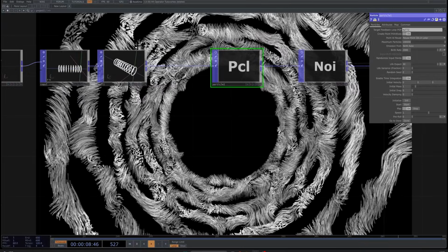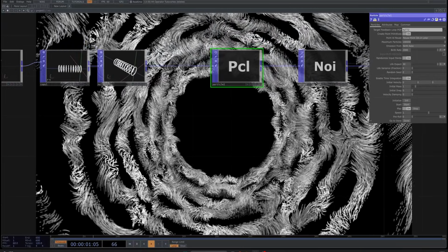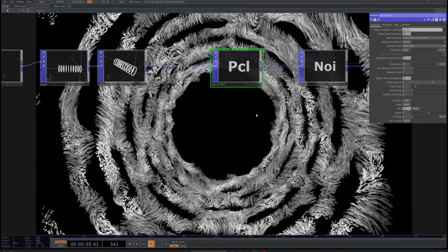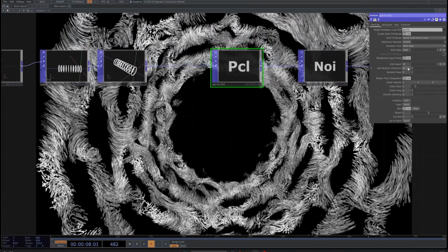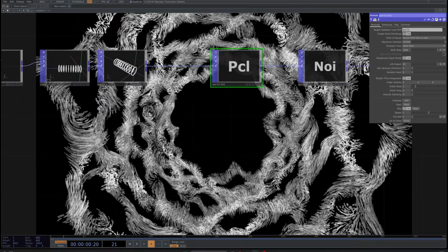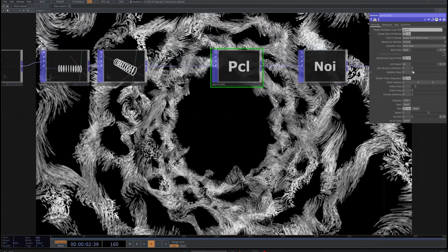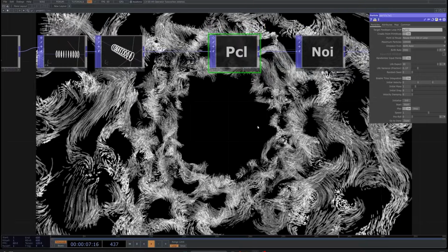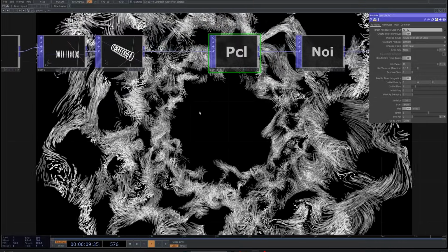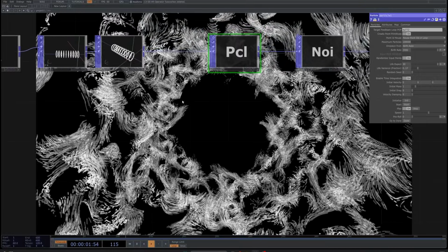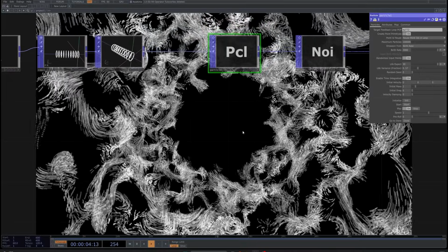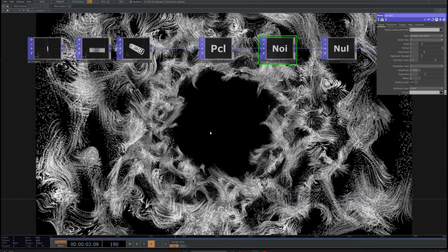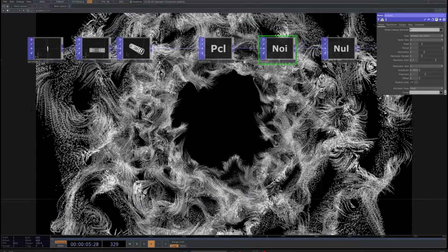And now the system is such that each particle has the same duration or same birth rate. And maybe I want to differ it to have something a bit more organic. So in life variance, it's a fraction. I'm going to change it a bit, to increase it to something like maybe 0.17. And yeah, now you can see the system is really starting to take place. So now the system is working, but what I want is a bit like